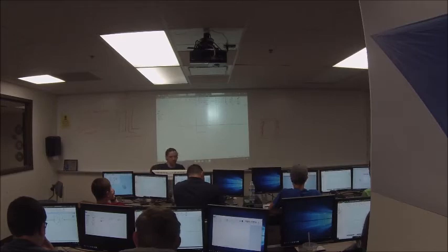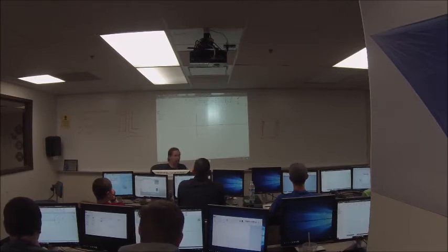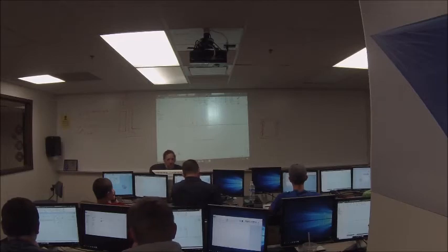Because for instance, let's say I created this part here, right? Actually, one quick thing before I do that. Coincident constraints, you can also place another way by typically just clicking and dragging. Like I talked about last week, your parts always need to be what we call fully constrained. So if I made this part, let's say it's a triangle, let me make a triangle here.